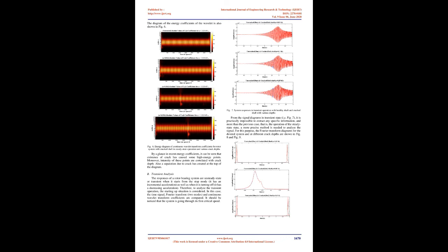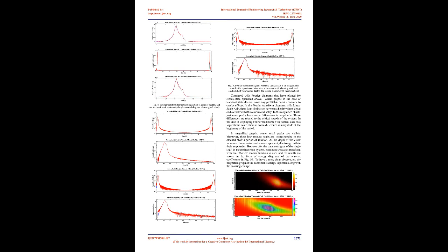From the recent diagrams, it is obvious that the Fourier transform diagram, when drawn without magnification, does not have the appropriate resolution in linear axis mode, but after zooming, it is observed that as a result of cracks and breathing behavior, the peak is related to 2x harmonics. It is easy to see that it was previously considered a sign of crack in the references.